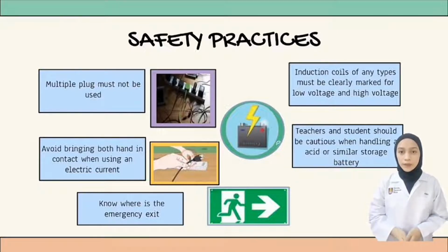Then, avoid bringing both hands in contact when using an electric current. This minimizes the danger of an across-the-chest path for electric current. It is best if you can work with one hand when you work on a live power circuit. Other than that, the lab assistant or teacher must mark the induction coils with high voltage or low voltage.